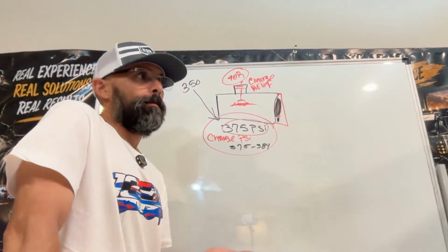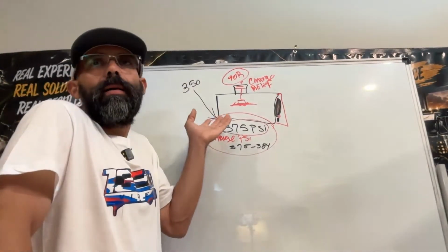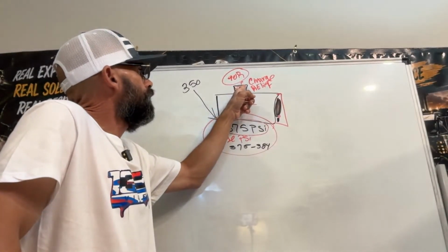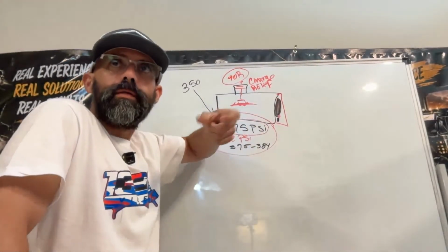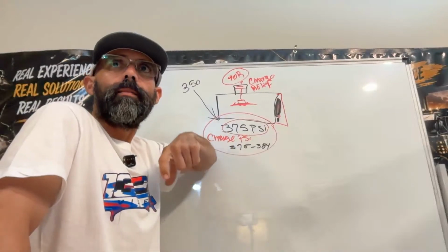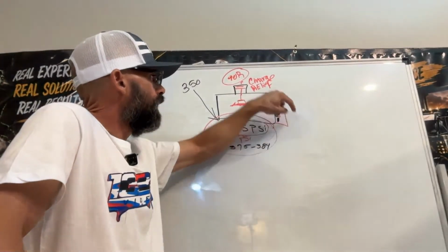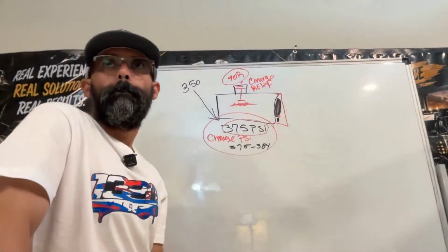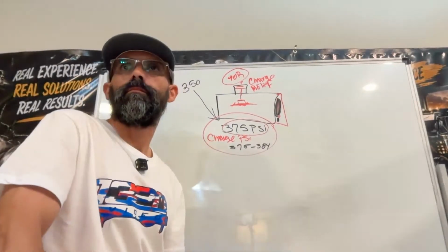But what will happen if you keep adjusting up, clockwise, the charge pressure and nothing happens? Well, maybe you have a bad charge pump. Maybe.